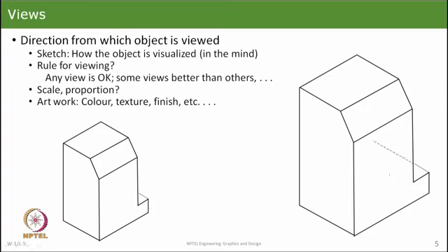So, let us see now what are the hidden lines in this. That is the first thing. We say, well, this edge actually goes back all the way. So, that is the dotted line. Then we say that since this is a rectangular strip which we see from the top, it will have all these lines which completely tell you that there is this surface on the back side of this object.